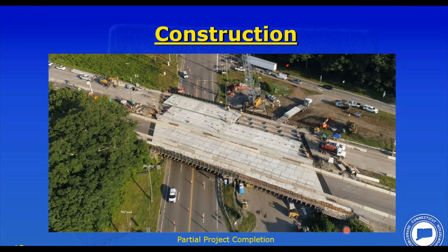Yeah, the answer was there were closure pours done at the end of the bridge. The design team, I think, investigated the use of trapezoidal shaped panels. The thought was with a 7-day closure that some cast in place construction was reasonable as long as most of the deck was precast.